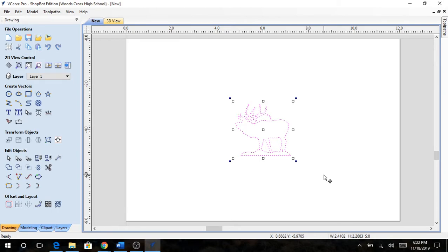You can see down at the bottom of the screen, as we drag across our board here, it's just giving us a list of coordinates on our graph. So what we've done is now we've created lines that have points on our graph, and the software can recognize that and follow it when we create our toolpath.